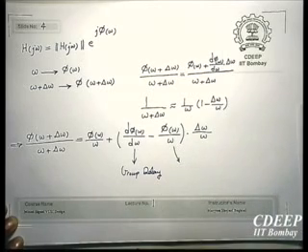You can calculate d phi omega over d omega for a range of frequencies. If it is constant for a range of frequencies in the passband, then you have a linear phase. If it is not, you always want to make it linear, so you want to make this constant and smooth, and this is phase delay.